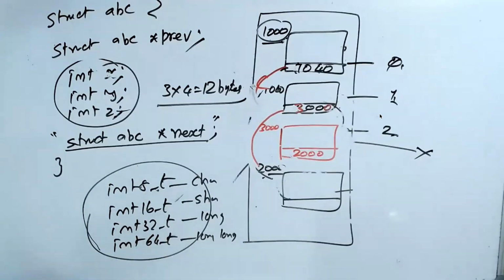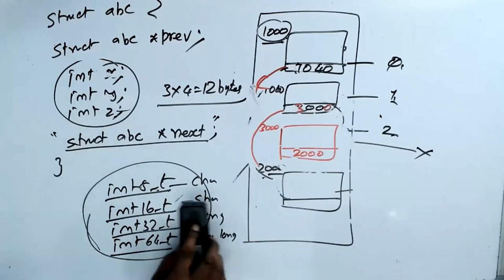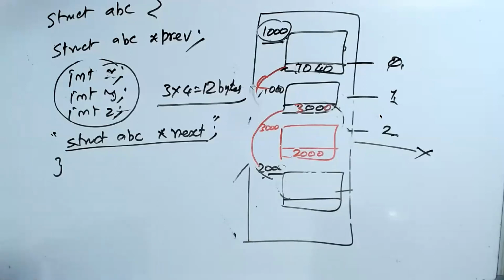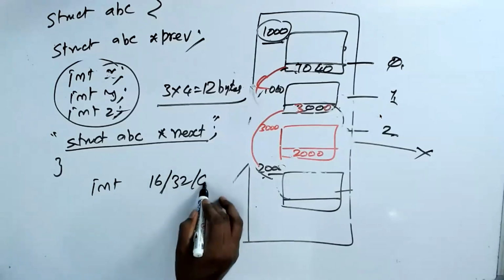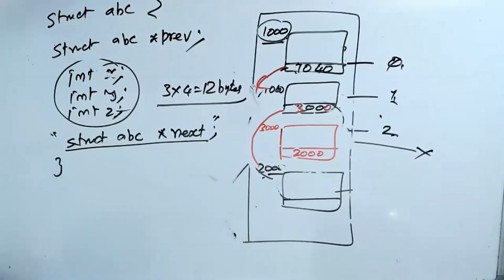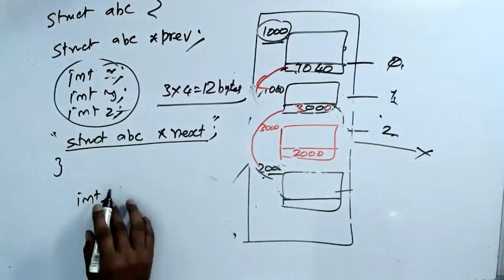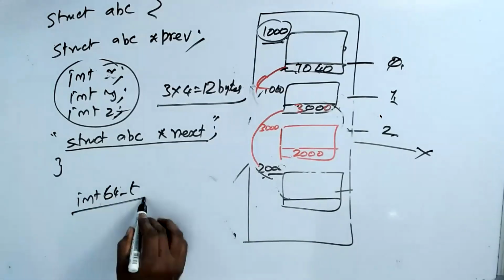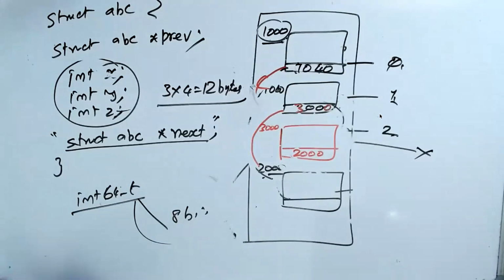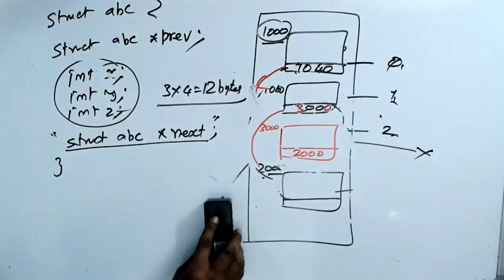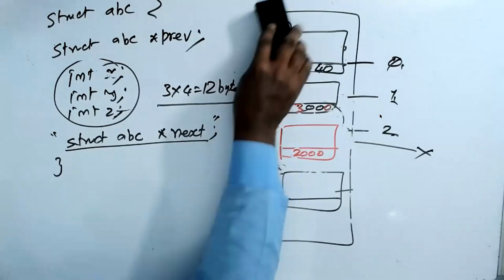So understand now. That's why companies everywhere, you will start seeing this nowadays. We don't use long, char and everything, because the confusion will always be there. You will always be asking whether int is 8-bit, 16-bit, 32-bit or 64-bit. Whereas int64_t is independent of that. This is always 64, whether you use it on an 8-bit controller or any compiler. In any compiler you use, this is the way. You had better use this. This is the trick here.